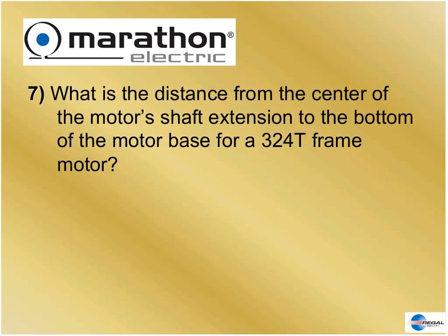Okay. What's the distance from the center of the motor shaft extension to the bottom of the motor foot of a 324 T-frame motor? Okay, let me think what he said. Three digits. What do I do with three digits? Okay, well, I got four digits there, but the T doesn't matter, does it? No. Okay, it's 32. What do I divide by? 16? No, that can't be right. 32 divided by 4 is 8 inches. That's an 8-inch center shaft motor.